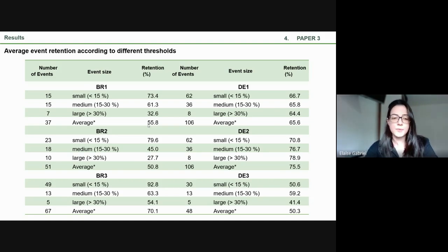For the German green roofs, the retention values varied from 20 to 71%, and the rainfall depths ranged from 1.2 millimeters to 81 millimeters. The German green roofs presented closer retention percentages for each event category, possibly due to the lower rain intensity in this climate.